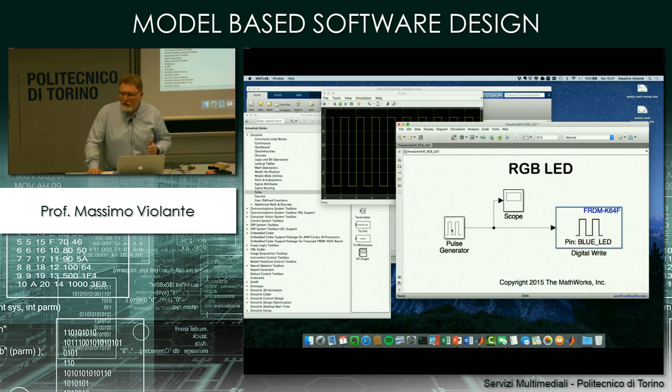So here we have a pulse width modulation that we can generate on the board to take control of one actuator, okay? For the moment, instead of mapping this output on any of the IOs that are available on the connectors of the board, I just want to drive one LED so that I have a visual feedback of what is happening.